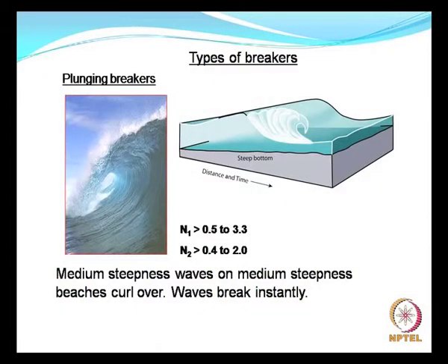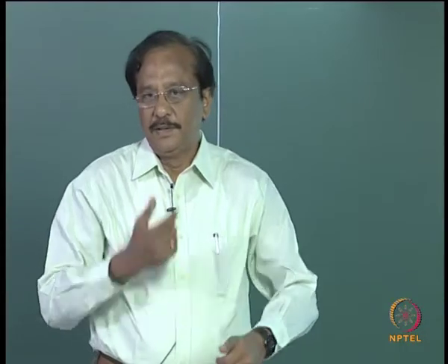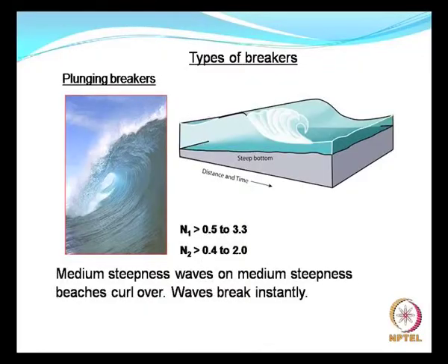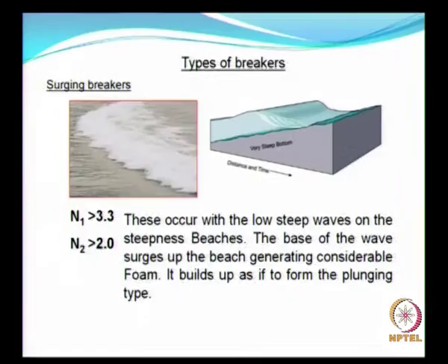Then comes the plunging type of breakers, and I am sure that you would have seen a number of advertisements wherein you have plunging breakers. It looks very nice, and when does this occur? When medium steepness waves are on steep beaches, the waves curl around, and the breaking is instantaneous. It instantly breaks, and it also creates sound when it breaks.